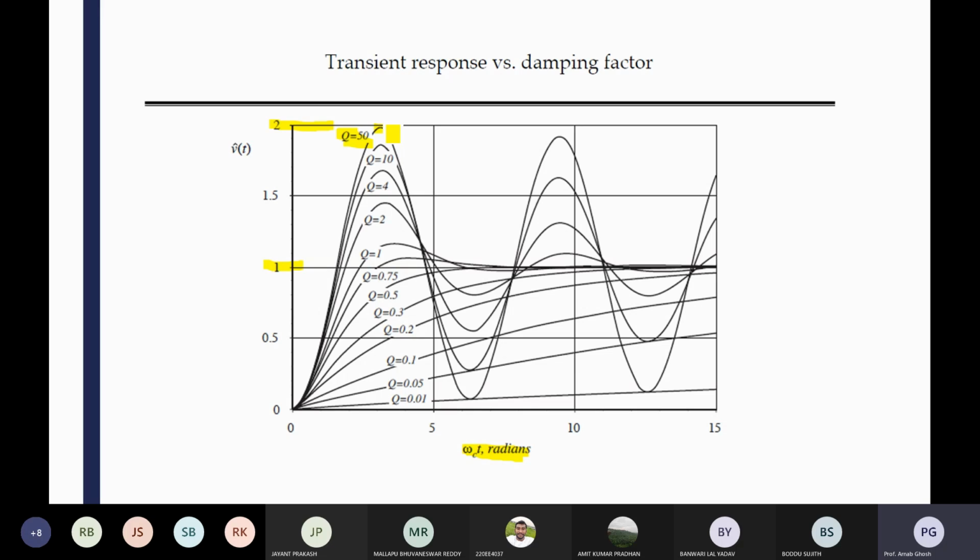So a very high Q value is not acceptable. Again, a huge value of Q means less phase margin. So Q should be moderately low, more or less nearer to 1. You can see that the Q value is 0.5, a very good value. That 0.5 value is more or less critically damped. Your aim should be that your system is critically damped, so it will not be underdamped or overdamped. It is more or less critically damped, so there will be no overshoot, no undershoot, and no steady state error. That is your consideration.